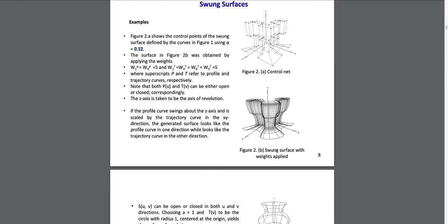So the generated swung surface appears to look like the profile curve if you look from the front, like if you look straight towards the z-axis from the xy plane, and it looks like the trajectory curve if you look from the z-axis towards the xy plane.